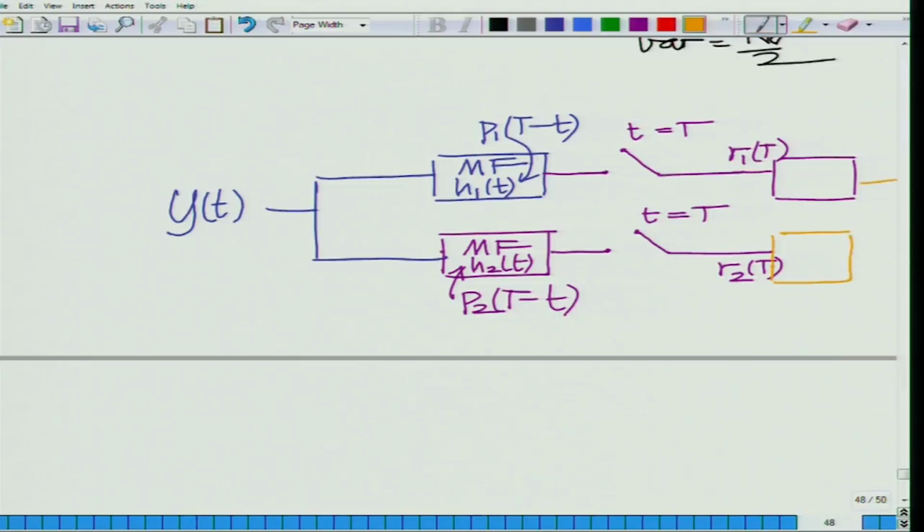device. Okay. So basically what this does is, if it is greater than 0, it decides plus A, less than 0 decides minus A. So this is basically a hard thresholding operation, this is the optimal decision rule. Okay. So this is basically the schematic of QPSK detection.